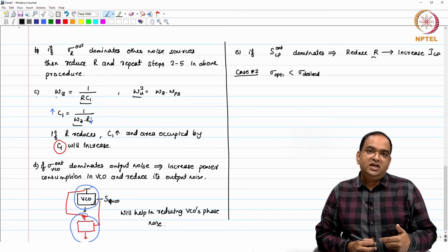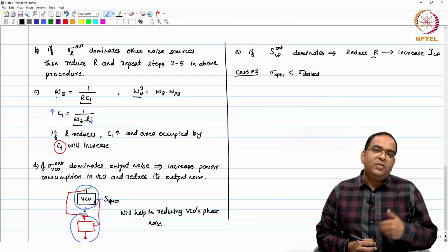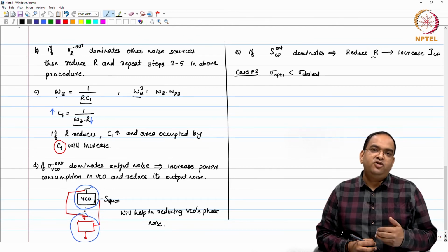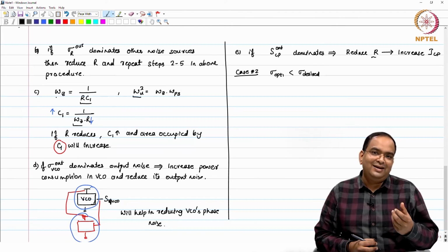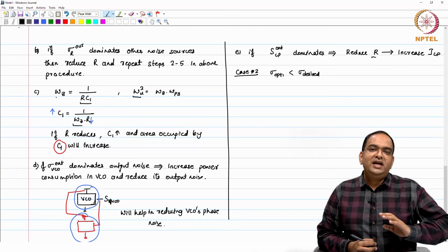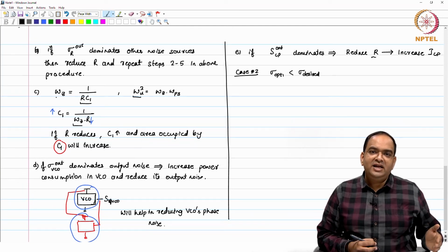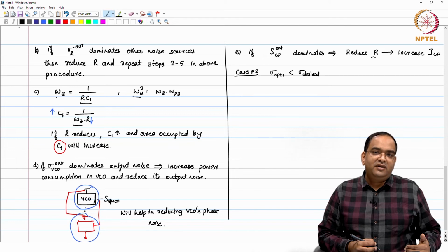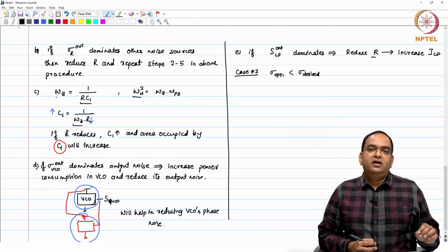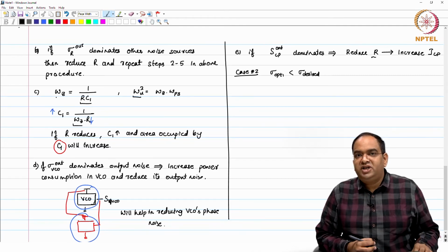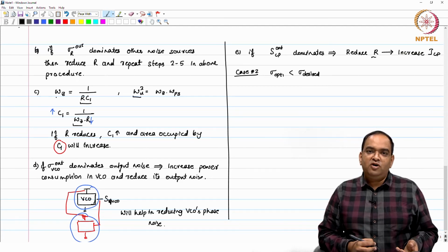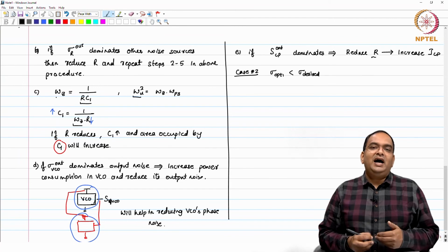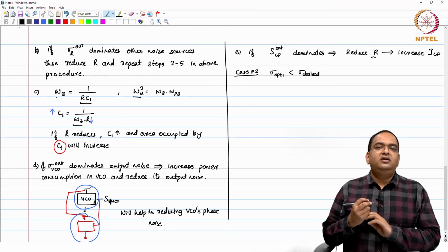if your jitter is lower, then by default you can think about it that your power consumption in the design is larger. So, it is like I need 2 picoseconds, I am getting 500 femtoseconds, right. So, I am spending power for 500 femtosecond, but my requirement is not 500 femtosecond, it is only 2 picosecond. So, if I try to get 2 picosecond of jitter, then I can reduce my power consumption.